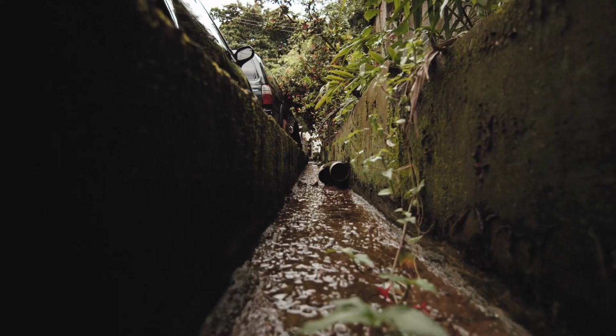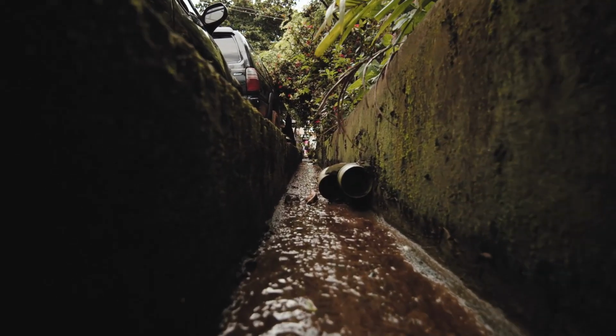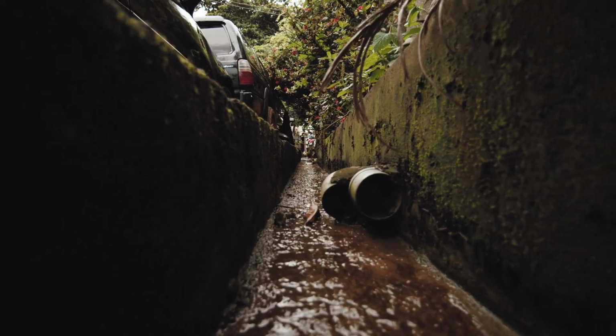We design the drains by performing a geotechnical investigation, normally called sieve analysis, whereby we analyze the size of the base soil which is surrounding that drain. This is normally achieved by a simple equation which states that the maximum size of the perforation should be less than or equal to D50. D50 is the grain size of the soil at 50% finer. It is achieved through the same test.